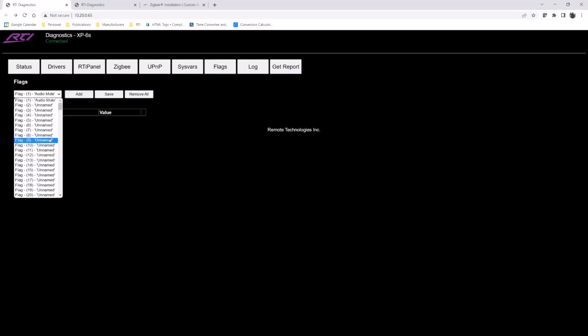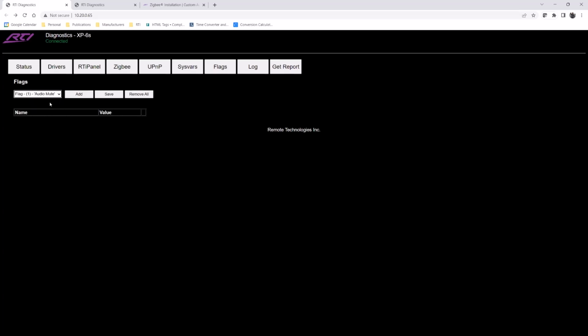You don't need to sift through everything that you have in there. You just want to test the certain flags, so you can just choose that XP macro flag. Now, keep in mind that this is the processor flag. This isn't the individual device flags that we're testing. If you're going to use internal logic-based flags on the device itself, that's going to be a little bit different, and I'll show you how to look for those as well in a minute.